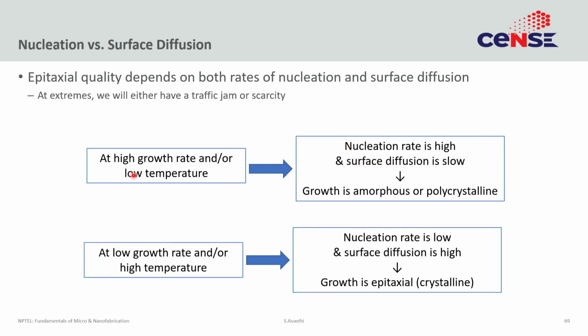Because it is either low temperature or you are not giving enough time for the nuclei to diffuse, because remember the distance that they will travel is some version of root D times t. So, even if D is large, but the time given to it to transport is very short, then it does not have enough time to diffuse. So, in some cases what is happening is you are piling up material so fast that the material does not have the time to reorganize itself on the surface.